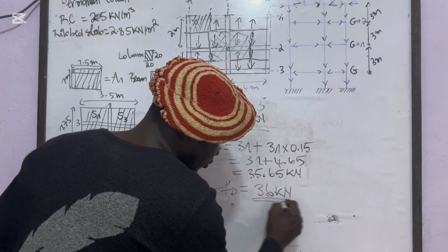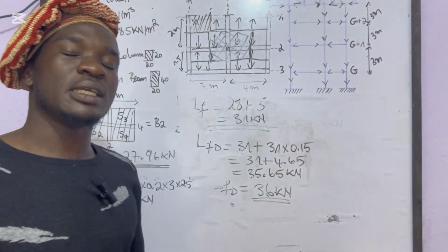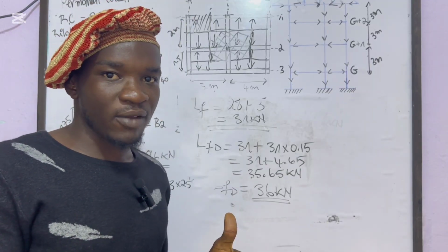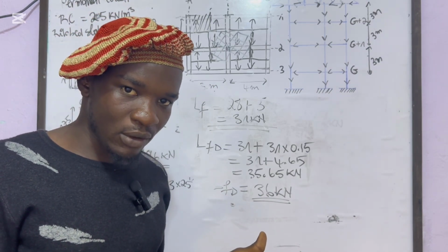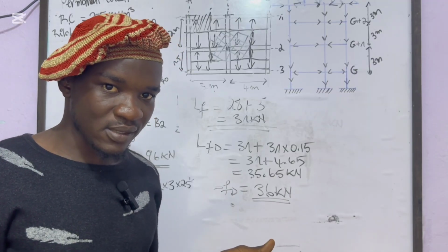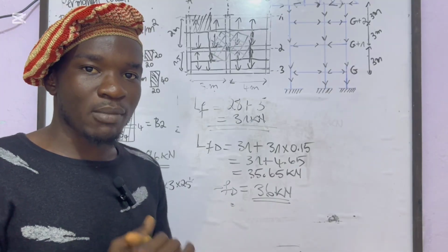It's better to just majorate it. Remember, even in using the norm, it is not for nothing that we have the safety factor like 1.5 for the live load and 1.35 for the permanent load, according to BIEL or to Eurocode. They have the same safety factor, though they might change at some level. So always try to majorate it, because